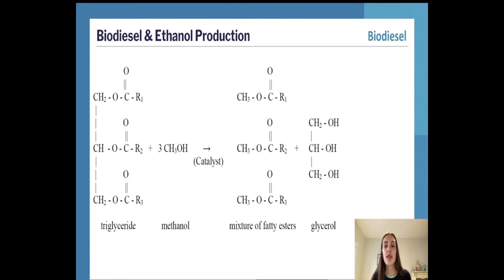Researchers have found that very good yields can be attained from using crude oils with lipases. Lipases, which are enzymes that break down fats, can make the reaction less sensitive to high free fatty acid content and water as well, which is a problem with the standard biodiesel process.